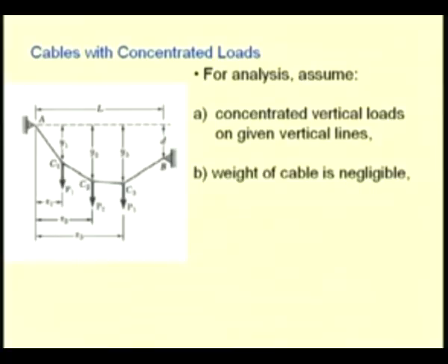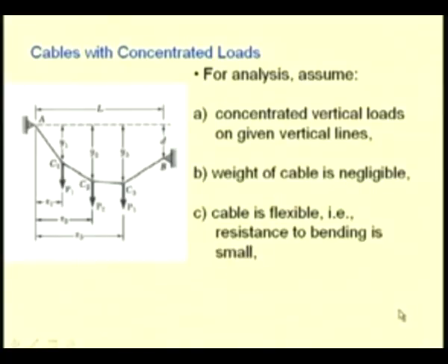Else the shape of the cable will be different if we also consider the weight of the cable, because it becomes a uniformly loaded cable in that case. But for the current analysis we assume the weight is negligible compared to the concentrated loads. And also the resistance to bending is very low for the cables. So, these end reactions will be only force reactions and not any bending moment.